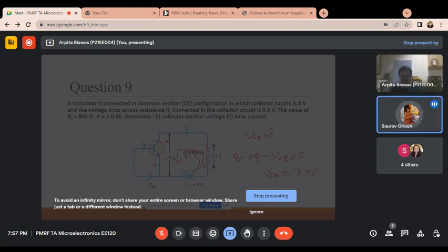And if we get the value of IC, then we can get the emitter current as we have alpha. So emitter current will be IC by alpha, and IB will be emitter current minus collector current. From here we can also calculate the beta value. Beta equals alpha by 1 minus alpha. Let's go for the easiest process. Here alpha is given, so you can directly find the beta, then from the beta you can directly get the IB value.